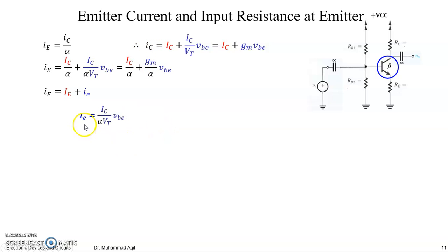So it means the AC emitter current, the current topic of discussion for AC modeling for small signals, we are having emitter current like this, right? Again, it is totally depending on this VBE, right? And this would be constant for a biased transistor, right? So instead of IC by VT, you can write gm, right?